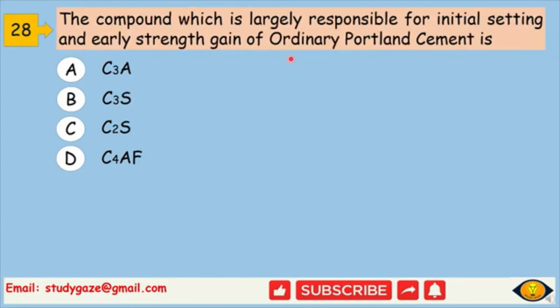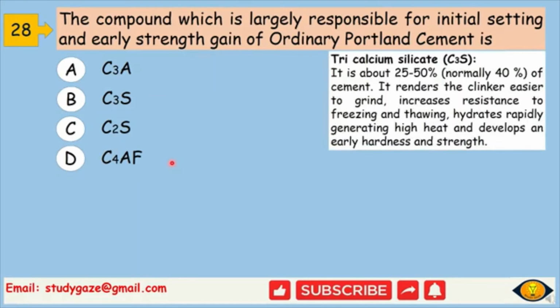28. The compound which is largely responsible for initial setting and early strength gain of ordinary Portland cement is C3A, C3S, C2S, C4AF. The answer is B, C3S. It is about 25 to 50% of cement. It renders the clinker easily to grind, increases resistance to freezing and thawing, hydrates rapidly, generating high heat, and develops an early hardness and strength.